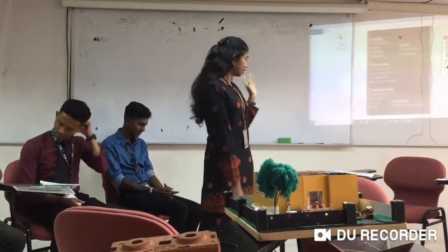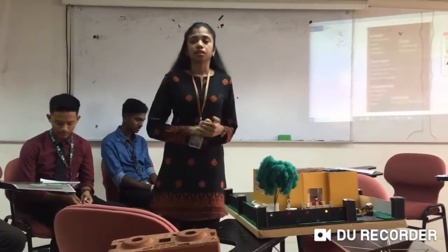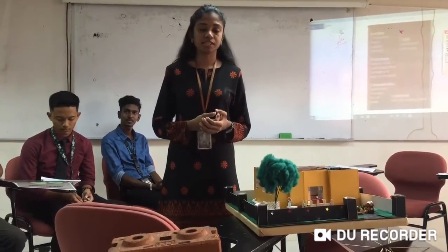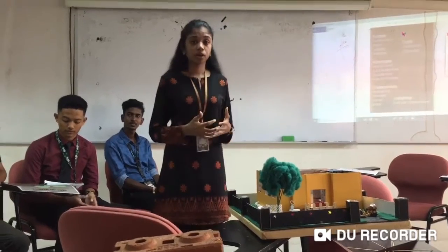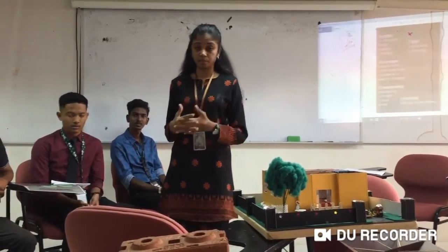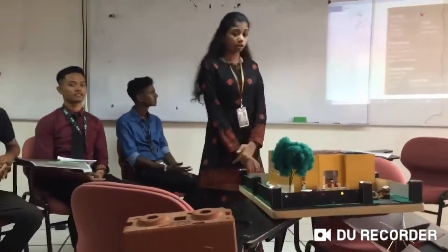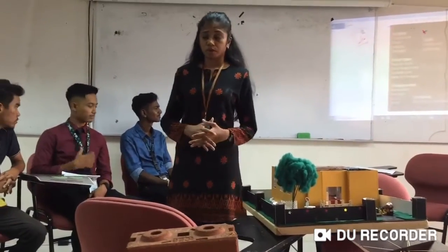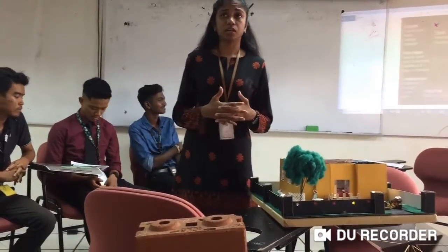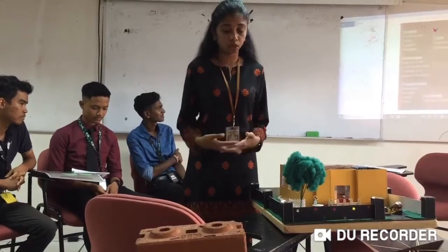When it comes to smell, a good timber usually smells sweet. A bad or unpleasant smell indicates a decayed timber. Let's see the appearance of the timber. How the timber looks: timber is shiny when it's freshly sawed.